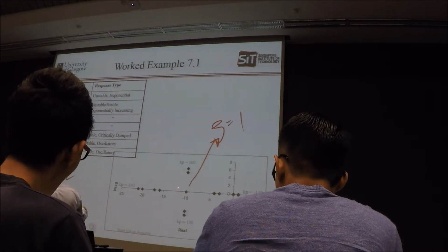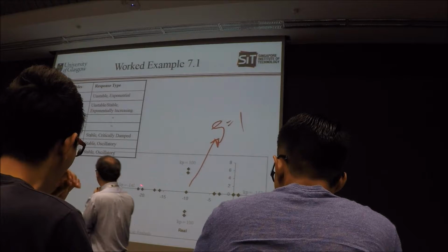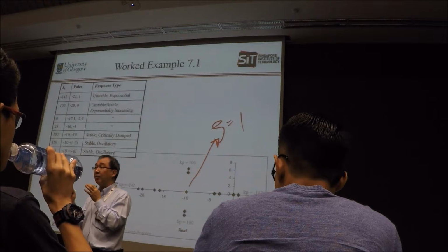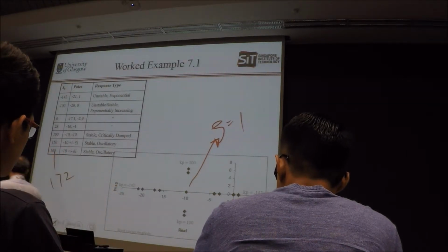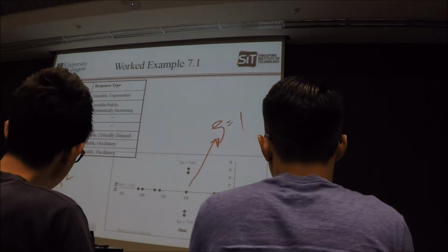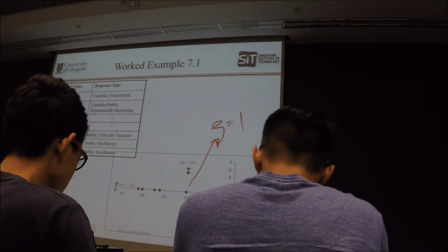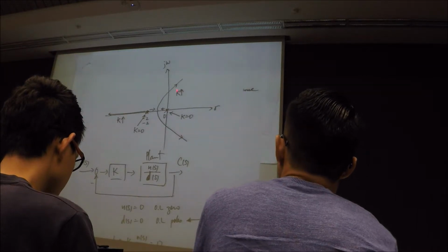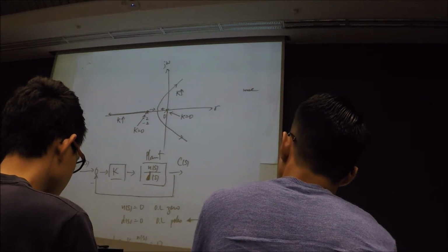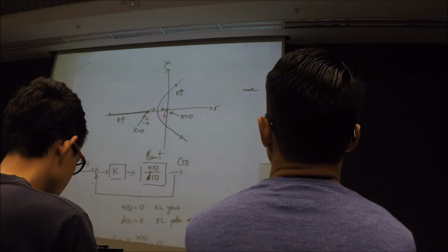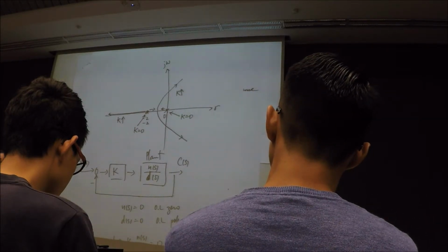Finally you can actually trace out all the dots, because you will have so many dots on the real axis and into the complex plane, and eventually it looks like what we discussed before, your root locus. Your root locus is if you combine all those points and plot them, making it finer and finer. This is your root locus. You no longer use point by point to indicate; you just draw a straight line, because this straight line represents many points in the complex S plane.